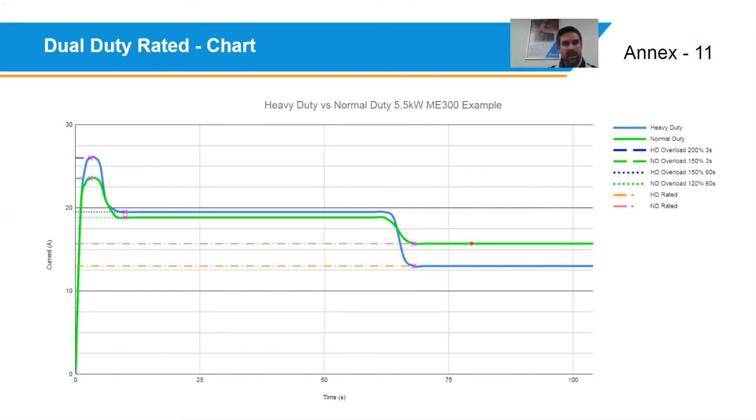In a pump or a fan, you've got a relatively easy startup. Because the startup is so gentle on the drive, it allows the designer to have a higher nominal running current. I hope this chart explains it. So like I said, compressors, crushers at that point.